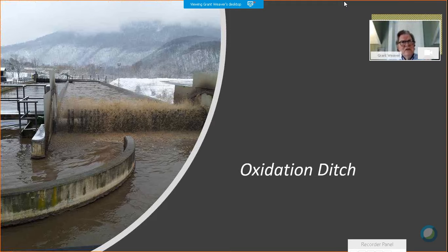If the transition of going from aerobic to anoxic starts to take more than an hour, you're just going to have a problem with nitrate removal during that cold weather. If you let that go too long, you're at the risk of creating septic conditions. I have a confession, I've done that, and I don't ever want to be there again. So, that's a great question, and it's one that I should have included in my discussion. Is there anything else?